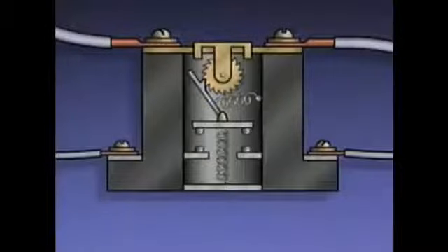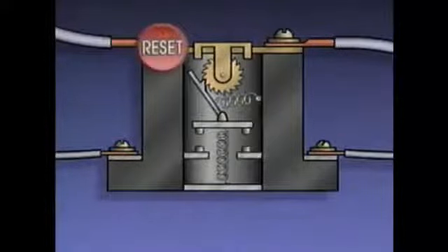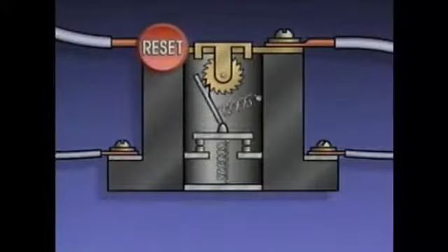When the current in the power circuit stops flowing, the heater stops generating heat. When the heater stops generating heat, the solder then cools and becomes solid again. When a reset button is pushed, the contacts of the overload device close, which makes it possible to restart the motor by supplying current to the M-coil.